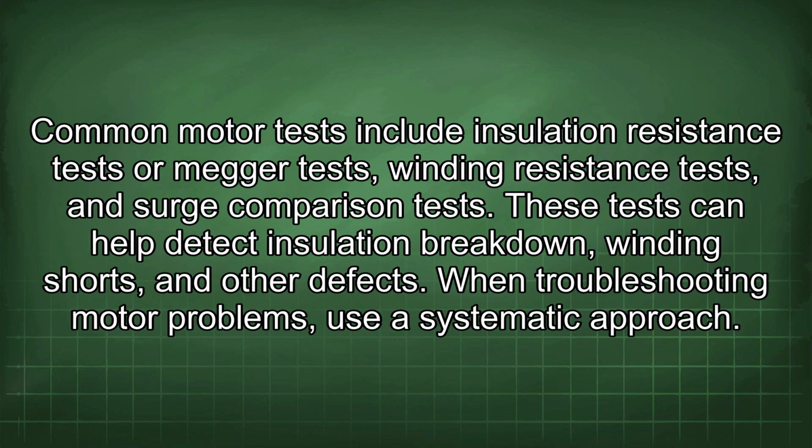Regular motor testing is recommended to assess motor condition and identify potential problems. Common motor tests include insulation resistance tests or megger tests, winding resistance tests, and surge comparison tests. These tests can help detect insulation breakdown, winding shorts, and other defects.